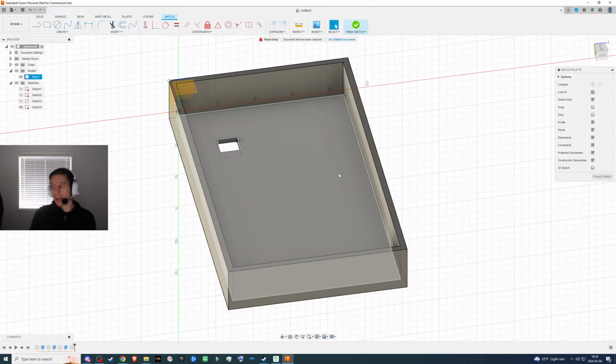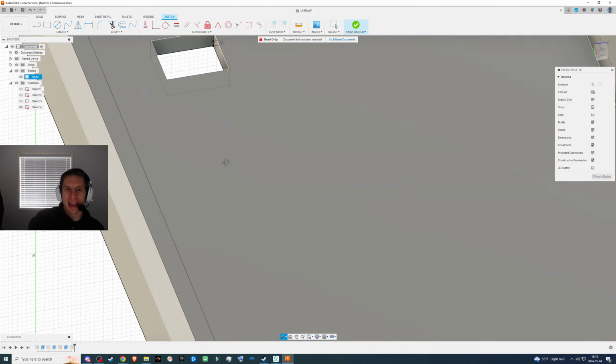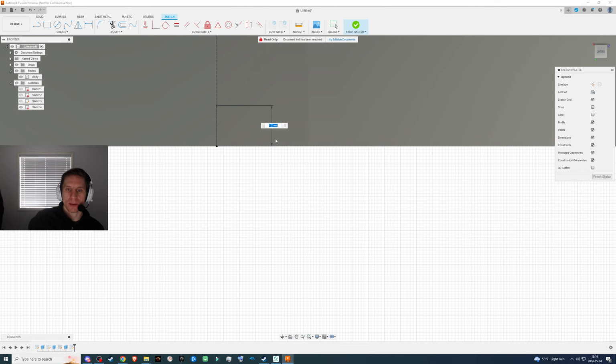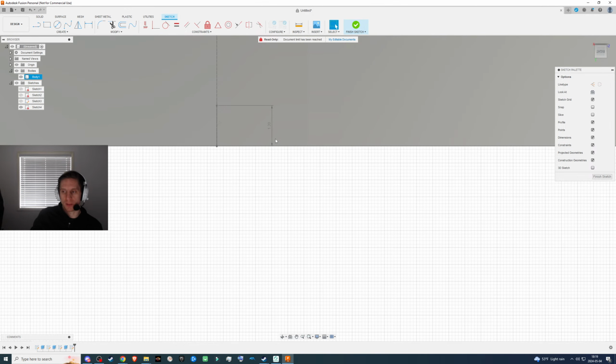0.1 millimeters is also very common. That would take twice as long, you can imagine, because it has twice as many layers. It is a cleaner print, but it takes longer. So if you were doing it at a 0.1 millimeter thickness, then we could make this something like 1.1. But 1.1 is not a multiple of 0.2. So let's make it 1.2, because that is a multiple of 0.2.